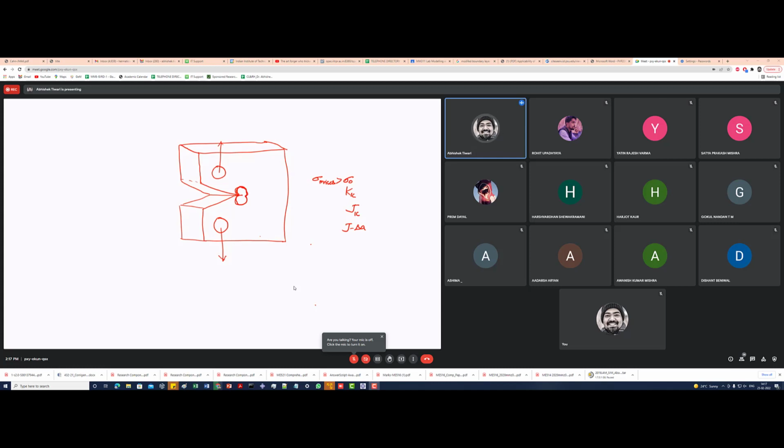And because the stress usually increases as you go near the crack tip, according to the theory of elasticity it should reach infinity, but it will get truncated at some point where the yielding hits, and then you have hardening rule and all those, and because of that you will be having a plastic zone, right?